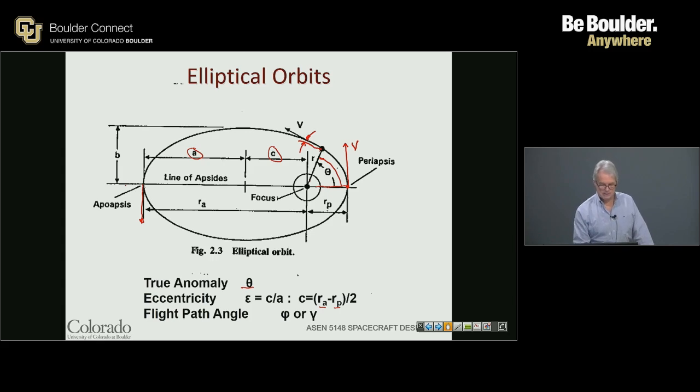These are key in terms of our ability to move from point to point, and if we can find points in the orbit where the velocity vector and the orbit itself are tangent and apply velocity change, we get essentially the best condition for moving, the most economical propulsive condition that we can have. And I'll talk a little bit more about that.